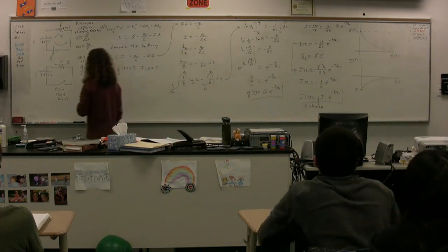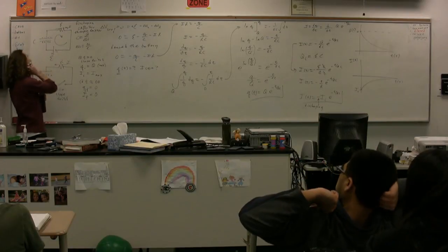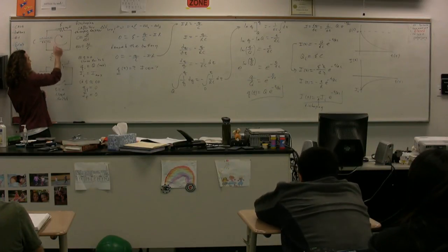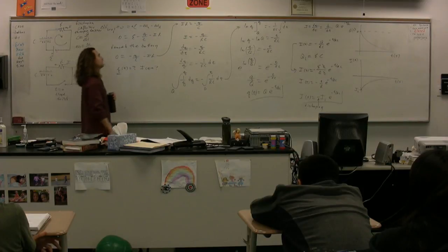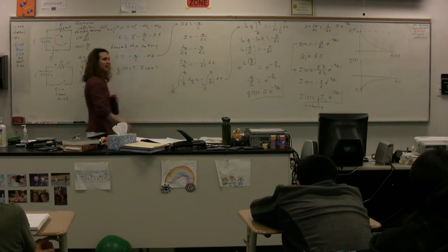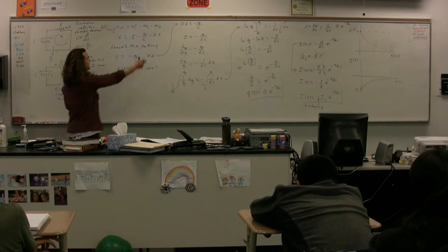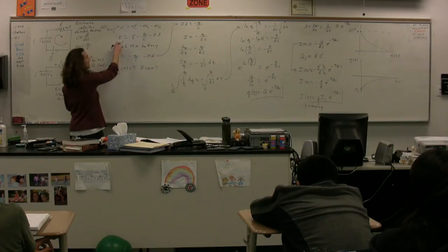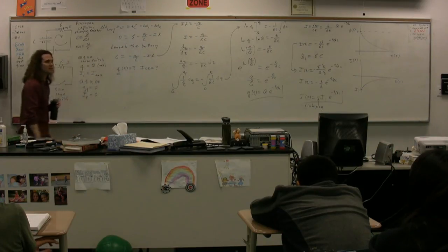We come back to, we need to know the charge on this capacitor. The charge on this capacitor was determined by the battery, essentially, right? So we have the battery in this circuit. After a long time, the current goes to 0, agreed? As we're charging the capacitor. So then current times resistance is 0. So you add Q over C to the other side, and the charge initial is just going to be E times C. So that is the charge initial.